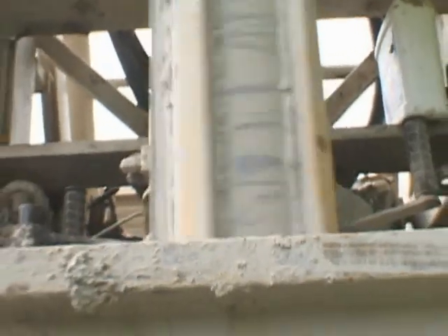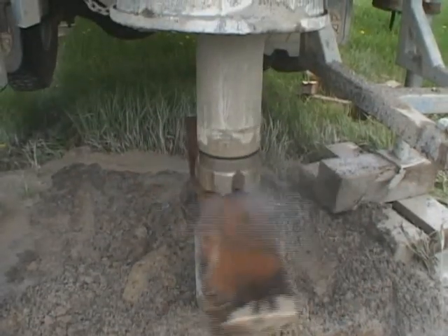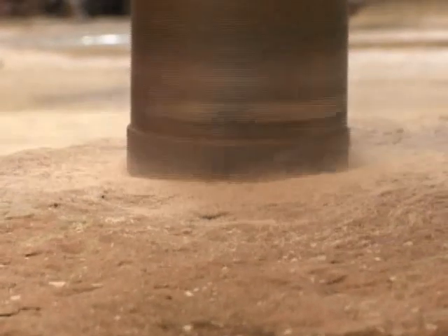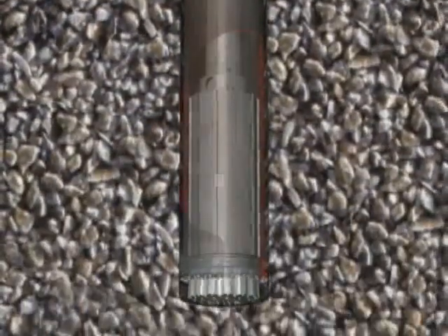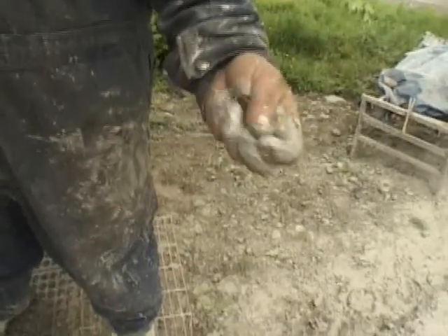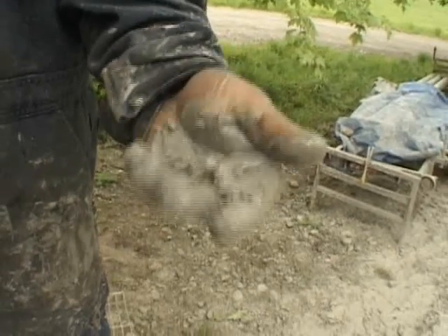The drilling systems profiled in this video all use one or more of the following 5 cutting actions, which are percussion, rotary percussion, rotary crush, rotary cut, and finally, rotary abrasive. The choice of the cutting action used is largely dictated by the geology of the formations to be drilled. For example, in soft clay formations, rotary cut is an effective cutting action. Rotary percussion, an ineffective cutting action.